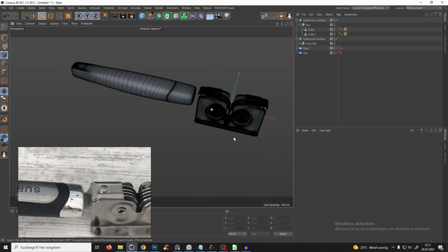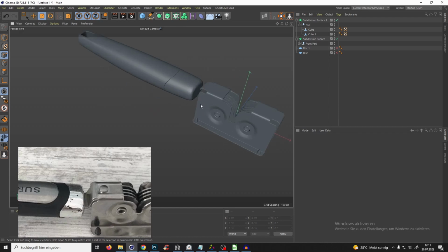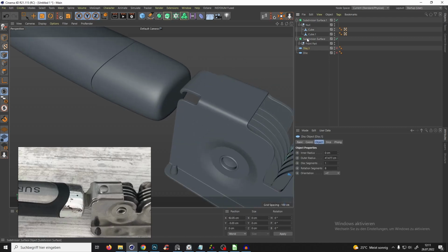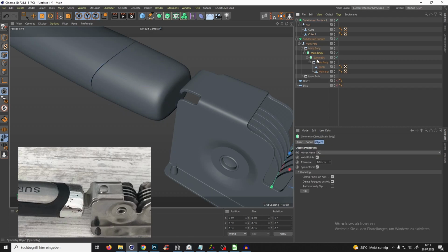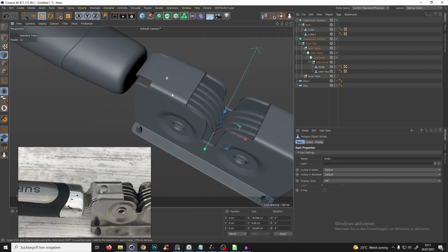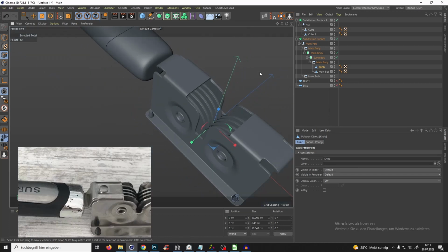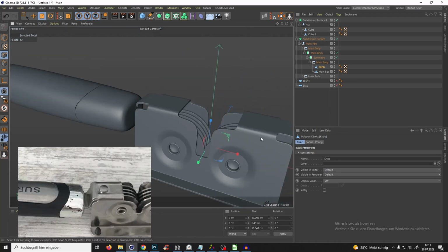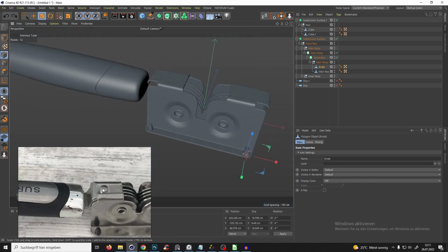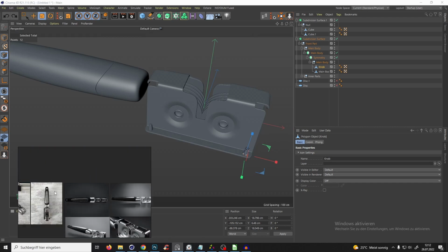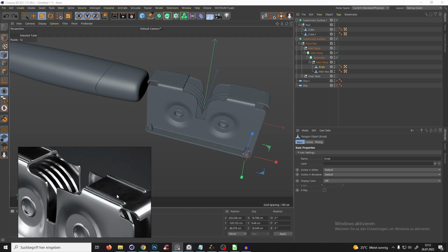And that's the stuff. We have this middle knob here, but again, you can just create it again. If we go to the main body, where is it? You can separate the symmetry object. So you have this as one object, you make it editable and just create with the circle. And as I showed you, like the knob here and those parts I created before, you can just extrude those extra polygons.